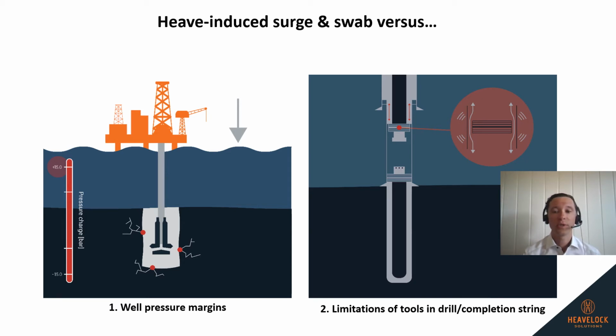What you risk if you exceed this flow in the annulus past the packer is that you preset the upper completion string. And there you can also calculate this limit. So how much rig heave is required to preset the completion string, and this will be your rig heave limit.